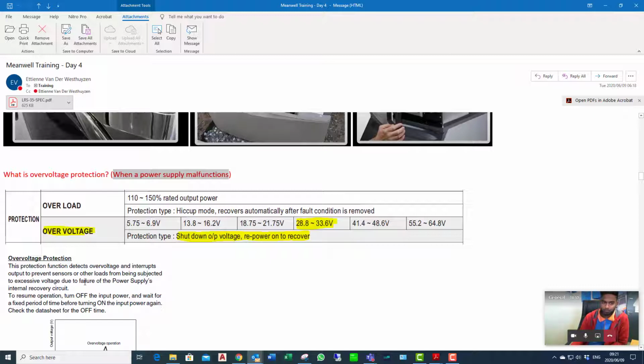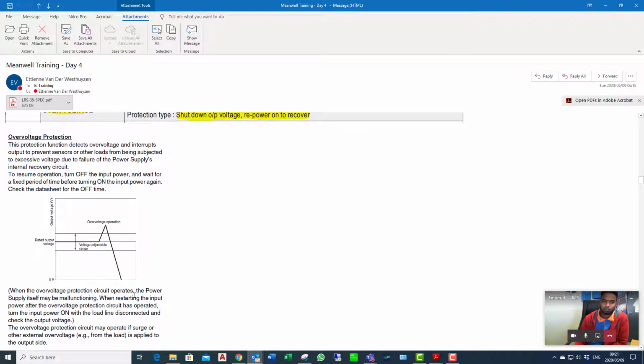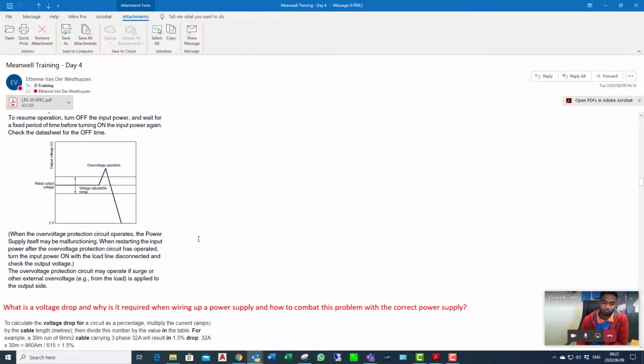So our power supply may be $1 or $2, which is a low value, but the equipment that is being connected to could be $1,000 or $10,000, and a slight overvoltage will pop that thing, which is $1,000 down the drain. So what MeanWell does is they offer that overvoltage protection. You would actually never see that in operation, because even if it does fail, the power supply would actually stop working. So it shuts down, and you'll always find the power supply rises again if you switch the power on and off, and it collapses again. They'll tell you the power supply is faulty. But at least you won't have a lawsuit on your hands of equipment being blown up.